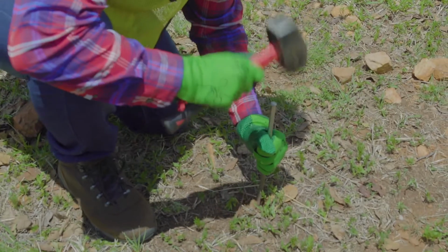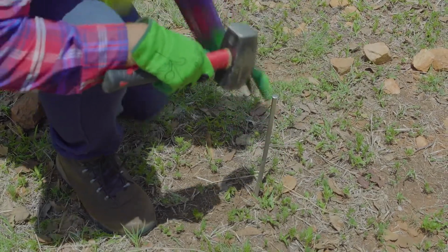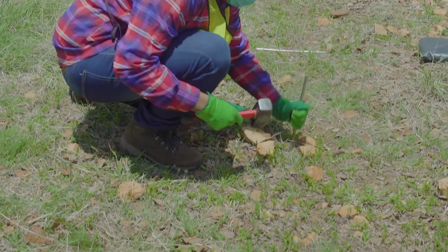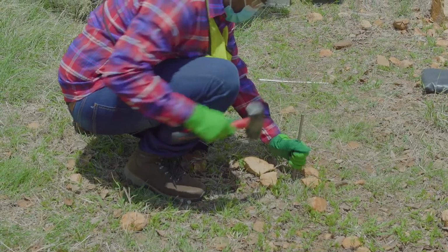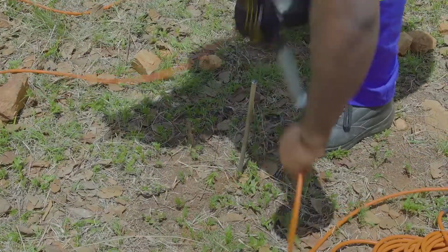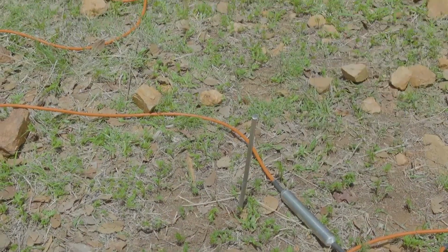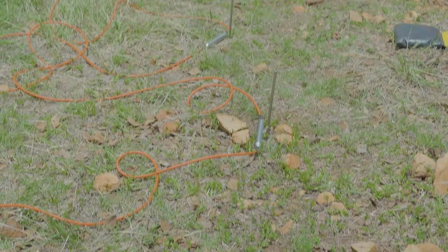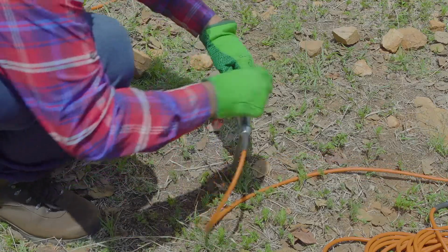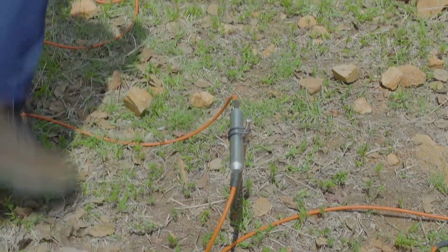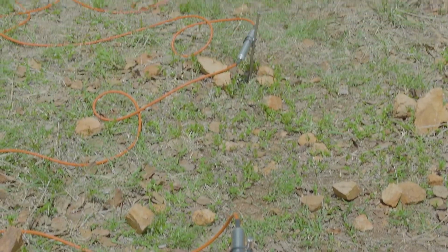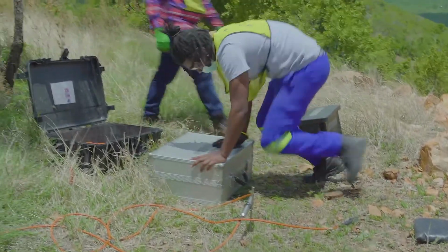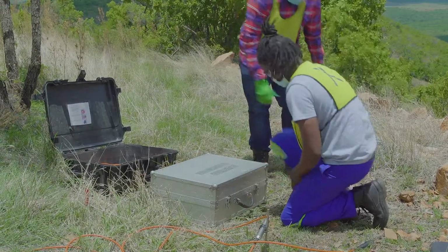To set up the resistivity survey, we first have to plan the profile. Once we've planned the profile, we first put in the pins into the ground using the hammer. Once that is done, we take out the electrode cable and place the electrode at each pin. We then take the O-rings and attach the electrodes to the pins. Once this is completed, we can connect the electrode cable to the AfricaArray meter box.